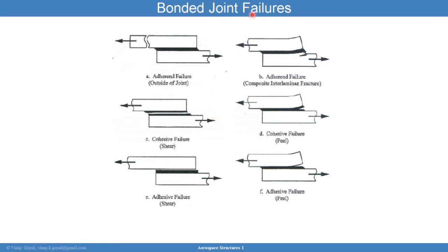Bonded joints are typically used in aircraft applications, launch vehicles, and spacecraft because they actually are good at saving weight. You can see here I don't have to put a bolt on. I have a part that comes in and is bonded with an adhesive. And that adhesive is usually strong, but not as strong as a bolt, for example. But it can carry quite a bit of load. And that loading condition can be such that it transfers the loads through the bonded joint, through this interface.